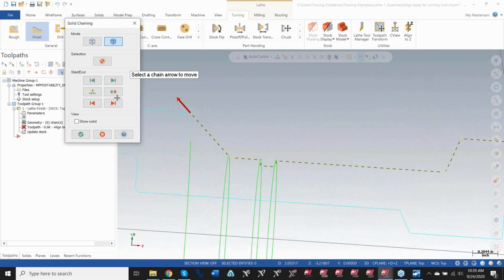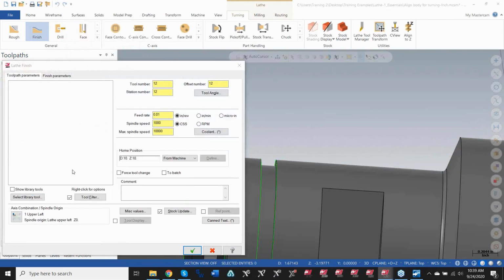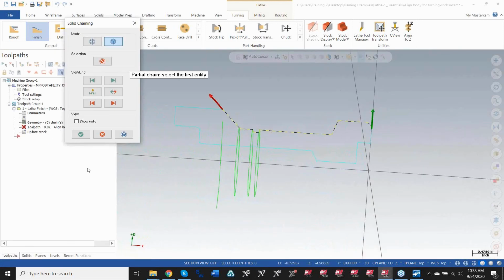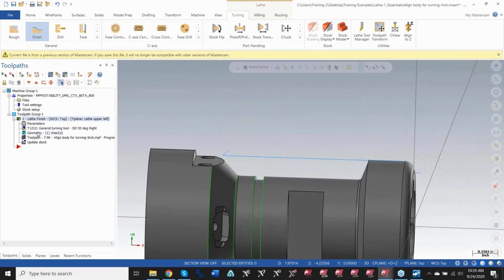Yep, and then here's that dynamics situation here. So if I go and just bring it to about there, that's where the toolpath will end up stopping, most probably. Let's see if I can make it behave. There we go. Stop midway through that profile. See how it stopped right there? This is supposed to go all the way up to about here, and I had it stop there. I didn't put any dips in there, so it didn't dip down. But you get the idea with the chaining.